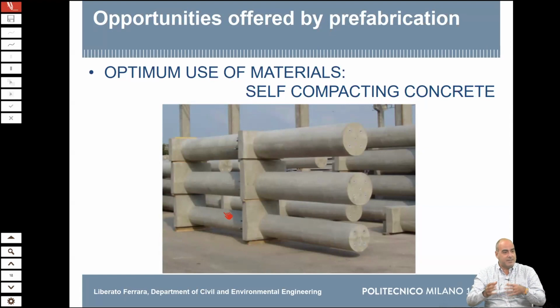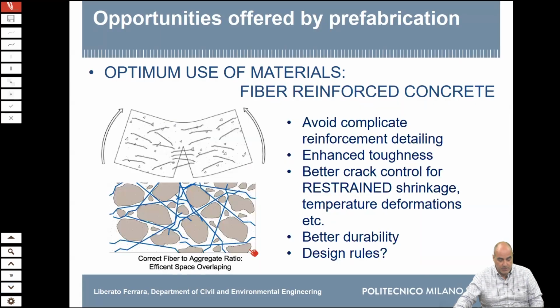They moved, and so we had an unintended failure mode because the stirrup spacing was not maintained during the casting. When you cast horizontally, it's first of all much easier to control, because you inspect it in line, but also you do not have this risk of displacing the stirrups because of the falling force of the concrete.